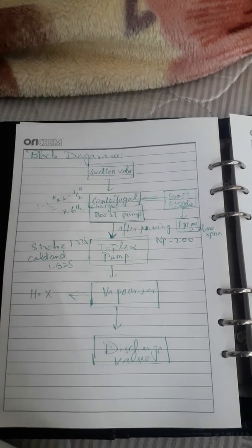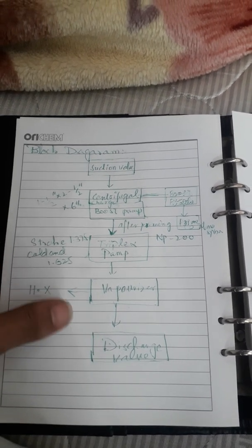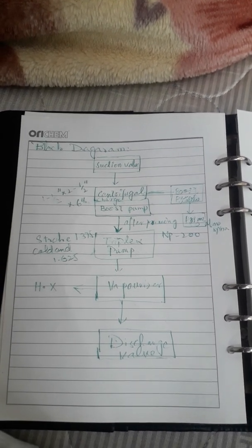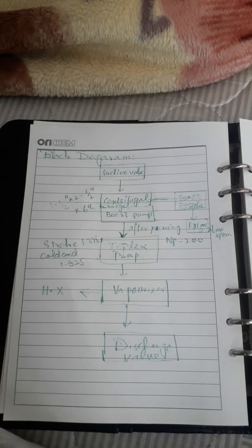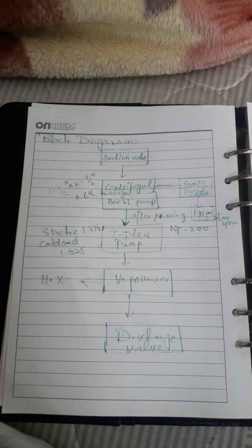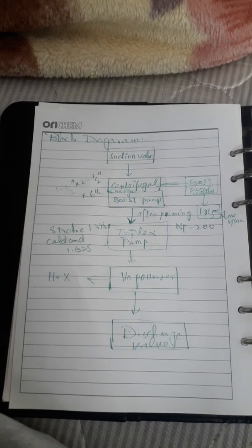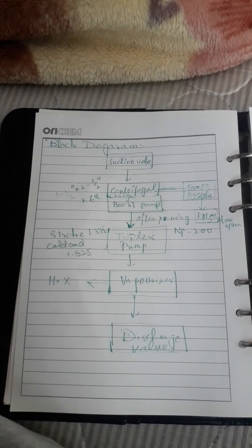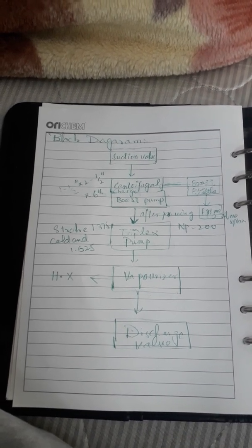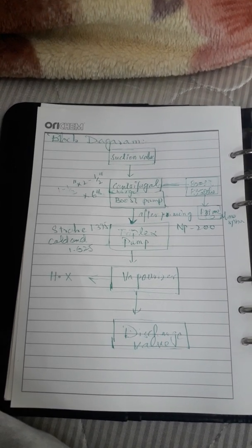Here we have a spherical shape with a tube bundle inside. Inside the tube bundle we have liquid nitrogen, and outside we have a shell side, which is flooded with waste heat generated by different processes, like the heat pump, like hydraulic oil, like lube oil, like the engine cooling system, and like the heat pump. There are 5 processes where the waste heat comes from, and it is flooded outside this one, to convert